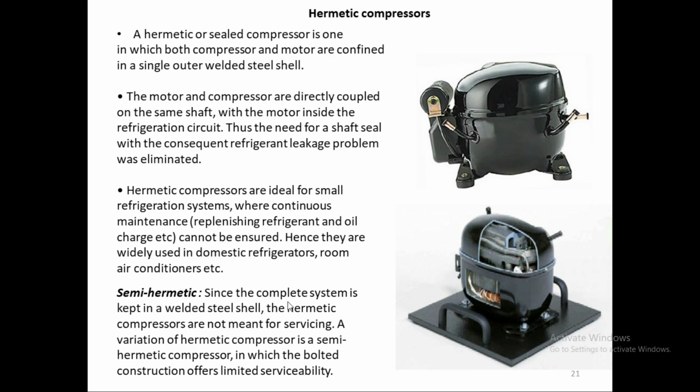Semi-hermetic, since the complete system is kept in a welded steel shell, the hermetic compressors are not meant for servicing. A variation of the hermetic compressor is a semi-hermetic compressor in which the bolted construction offers limited serviceability. So this one you cannot service because this is all sealed. This is welded together. The bottom part and the top part are welded together. So it cannot be serviced.